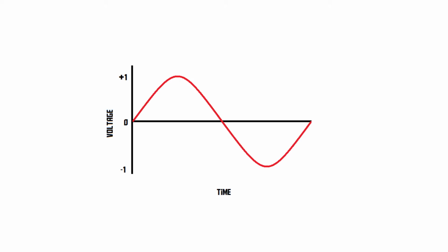We had a 1 volt AC sine wave, 1 volt peak voltage, which goes up and down, and we've calculated that the DC voltage that would give the same power dissipation, also known as the effective or RMS voltage, is 0.707. Right? That's how it works. It's actually quite simple. So that's simply what RMS is. RMS voltage is the DC voltage that would give the same power dissipation as that AC signal. And it's nice to have that because then we can perform calculations much more easily.